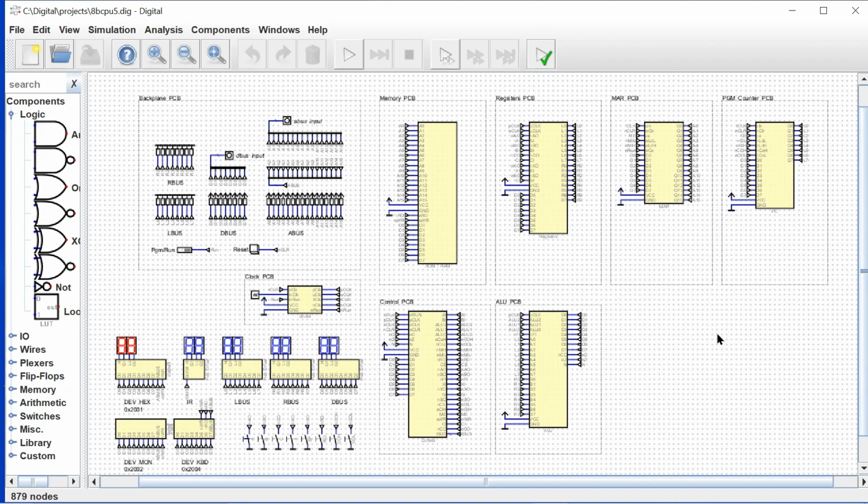Okay, so besides identifying the cards, the other thing that was important to do was to start to identify the inputs and the outputs for each of the cards, so we can start to look at and define the card edge interfaces for our computer. So that's something that's started and is still not completed, but it's looking like we're going to need 64-pin edge connectors for our cards, just because of the number of pins. And anyway, that's the way that's looking now.